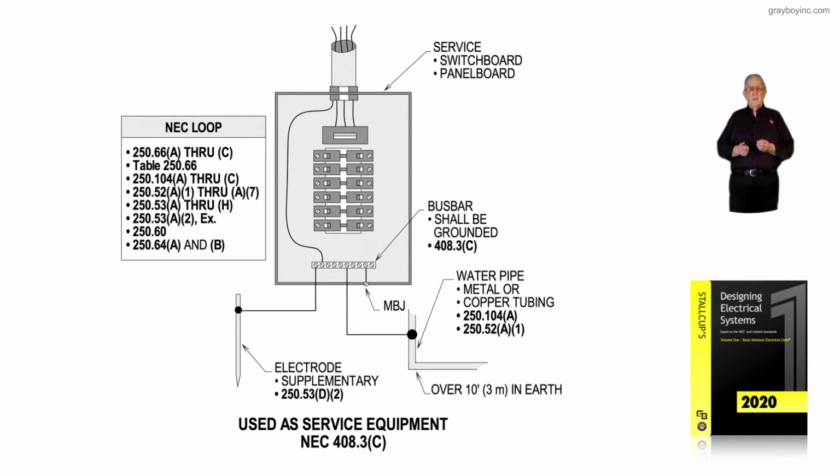Basically Table 250.102(C)(1) is an overlay of Table 250.66, but the items listed in the table address the grounded conductor, the supply side bonding jumper, and those types of conductors that are used to make sure the grounding of the service is proper.